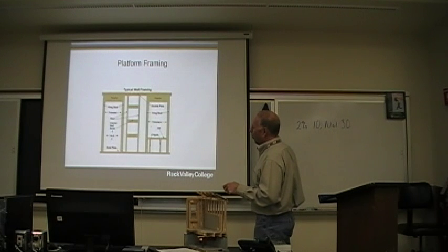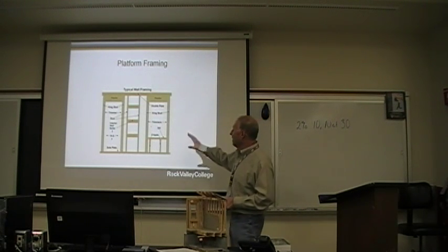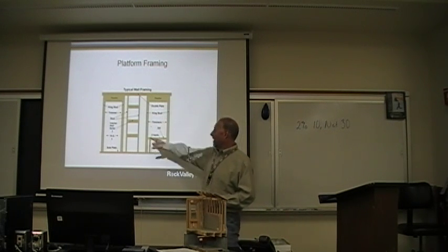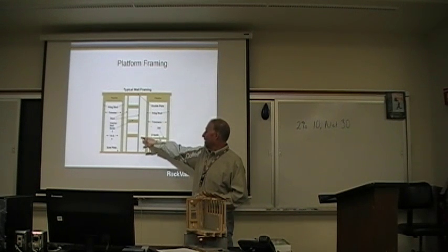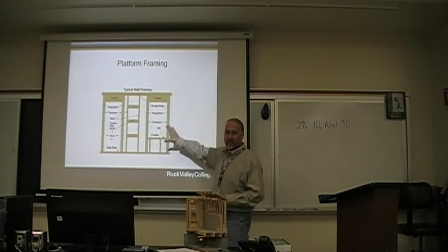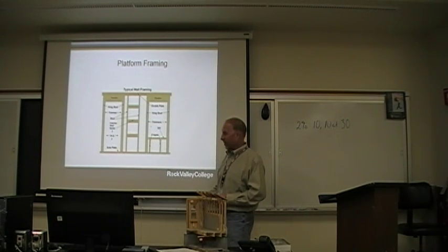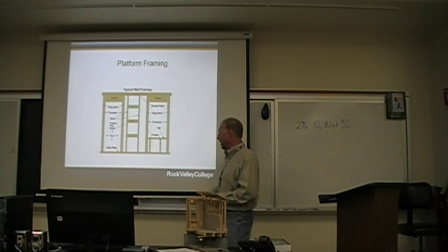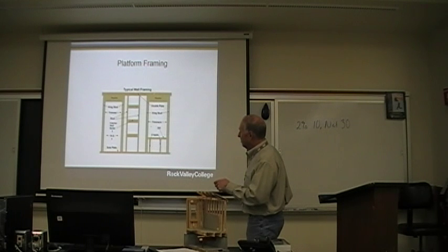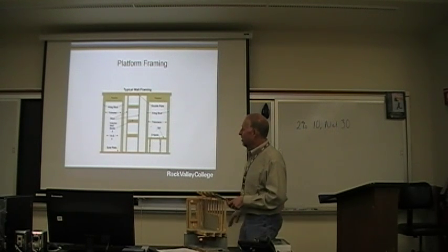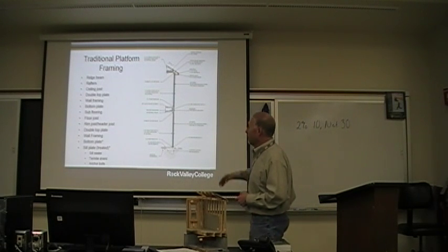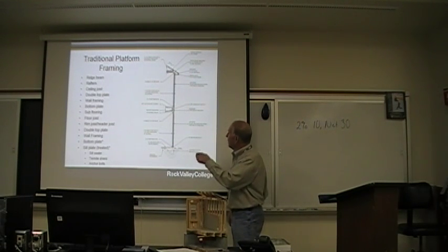These are our typical wall assemblies. Now this is incorporating door and window, and also some interior wall nailers or some bracing. But these are the kinds of things you're going to find in a typical wall assembly in a wood frame structure, platform framing. Bottom plate, double top plate, studs, some of the other elements in here, but typical wall framing.